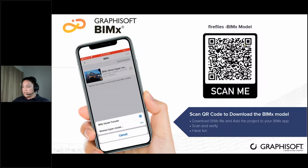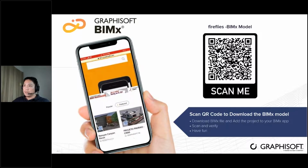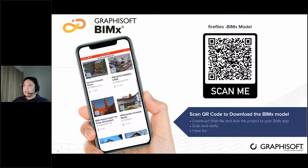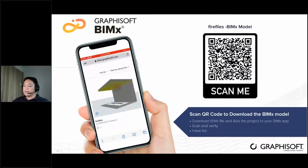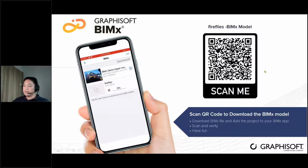Scan this one. First thing you need to do is go to your BIMx app. Click the plus icon and then go to the BIMx model transfer site. Search for the Firefly and start scanning the QR code. The name of the model is Fireflies, and then it will go directly to the website, and you need to download it. Just click download and open. If you scan the QR code here, it will direct you to the model and installation as well.